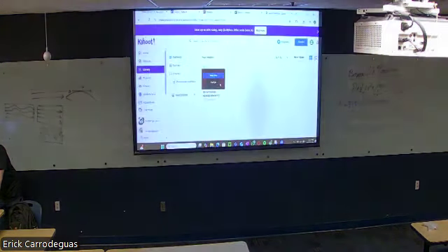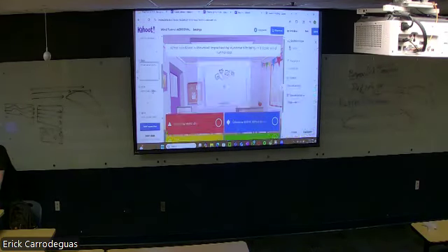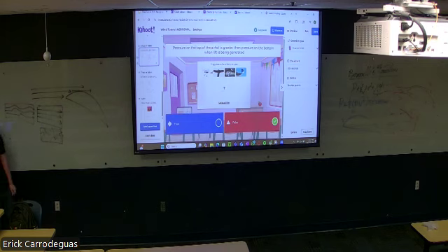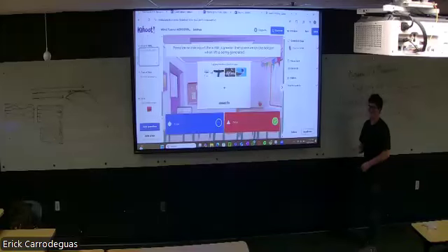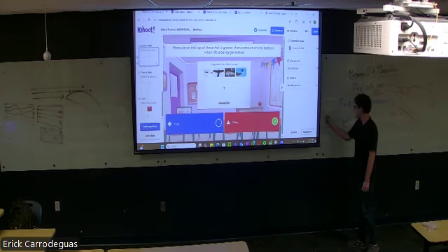The question: pressure on the top of the airfoil is greater than pressure on the bottom when lift is being generated. Isn't that false? Shouldn't the pressure on top be less? Yes. Oh my god. Yeah, sorry, it's due to the velocity. You have more velocity on top. The wind's faster on top. I'm going crazy. I'm sorry. I made these last night.